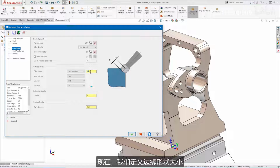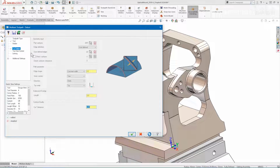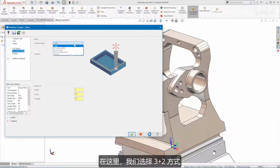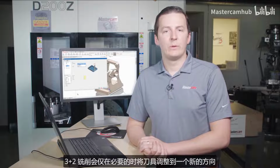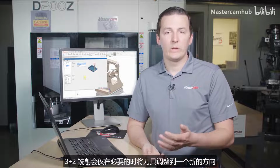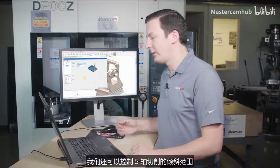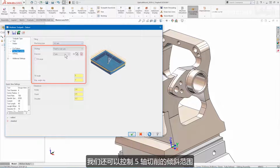Now we define our edge break size. On the tool axis control page, we define whether this should be a 3, 4, or 5-axis cut. For this sample, let's use 3+2. 3+2 will index the cutter to a new orientation for each chain only when necessary, cutting down on extra 5-axis motion. As you can see here, we also have control over the tilt range of the 5-axis cut.